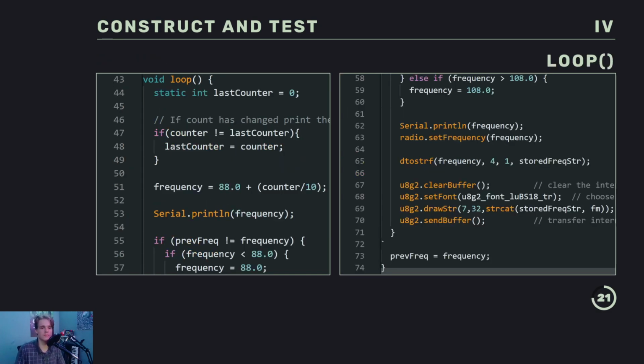There's a lot more here, but basically it's taking the input value from the rotary encoder from a certain range of numbers, and it's using math to convert that to the range that the FM radio module could read. It was doing that all through math, and then it was displaying it on the display. Unfortunately, I had some conflicting signal issues, an analog signal or something. So the radio signal would come out very distorted if I used the display.